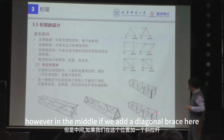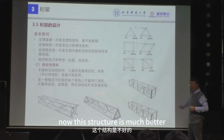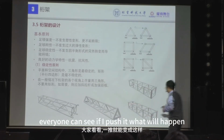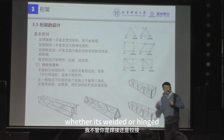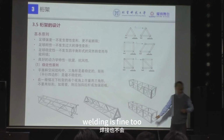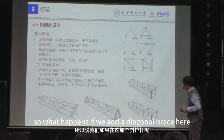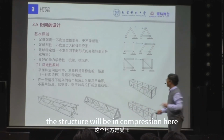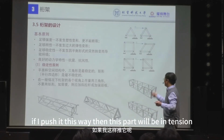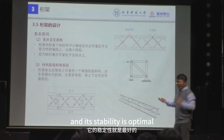If I push it like this, it could easily fall over. However, in the middle, if we add a diagonal brace here, it changes to a triangular structure. Now this structure is much better. Everyone can see, if I push it, what will happen. Whether it's welded or hinged, hinging is no problem at all. Welding is fine too, but the strength isn't very high. So what happens if we add a diagonal brace here? If we push it like this, the structure will be in compression here and in tension here. If I push it this way, then this part will be in tension. This ensures that there will be no deformation and its stability is optimal.